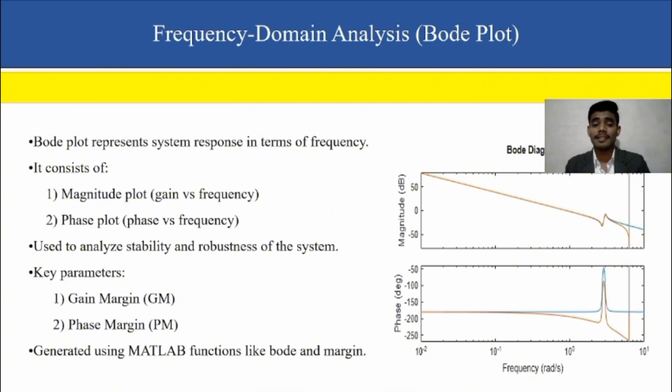It is used to analyze the stability and robustness of the system. The key parameters of the Bode plot are the phase margin and gain margin, and it is generated using MATLAB functions like bode and margin.